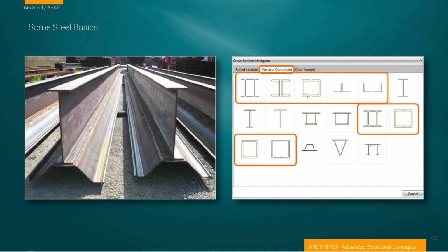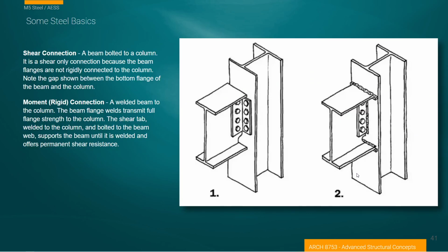But here's all kinds of composed welded sections. So two C channels together, face to face to make something that looks tubular, back to back to make something that looks like an I-beam. The combinations of I-beams, of L sections. There's a whole bunch of ways that you can build up these elements in order to create both the structural properties and the appearance properties that you would desire.